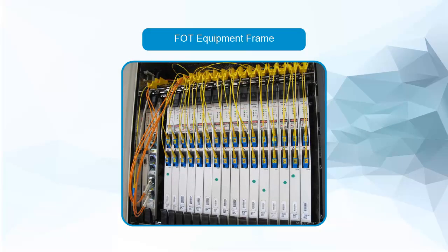As the network grows and evolves, new and different technologies will be incorporated into the FOT equipment frames, and the existing equipment will become obsolete or will be redeployed one or more times until the oldest equipment is discarded or all fibers are used. This network reconfiguration could involve moving large amounts of electronics and many long patch cords or reconfiguring short patch cords on the front of the frame. The ease with which equipment is integrated into the network and its potential effects on the installed network will depend on the fiber cable management system.